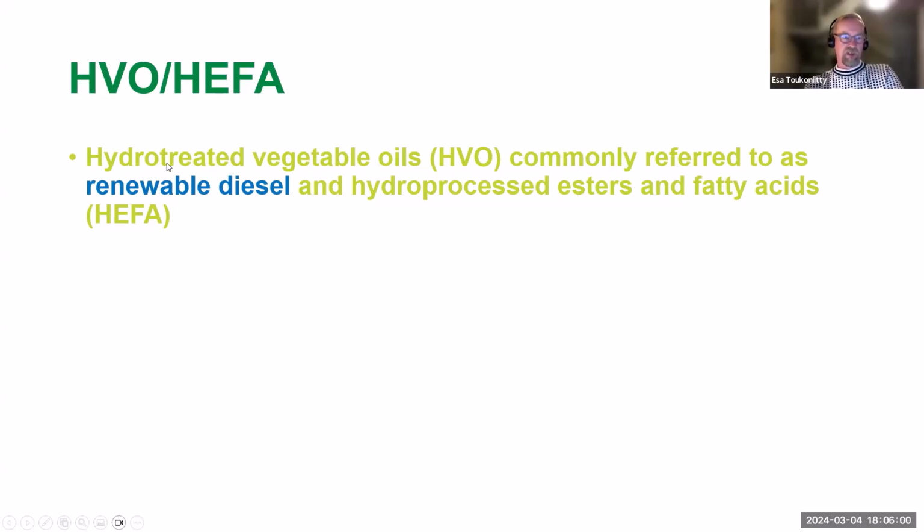So there is the hydrotreatment. It's treated with hydrogen in the presence of a catalyst. And what it basically does is it removes the oxygen atoms from the fatty acid esters. So you end up with the long hydrocarbon chains, which are the structures that are in normal diesel as well. And therefore it's better in quality.